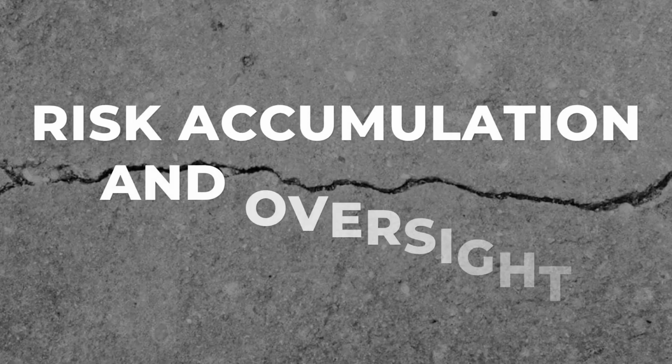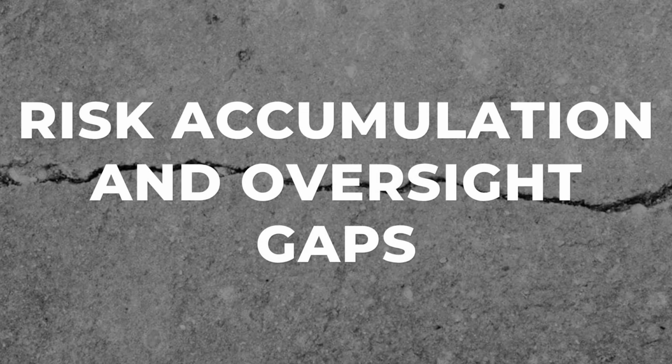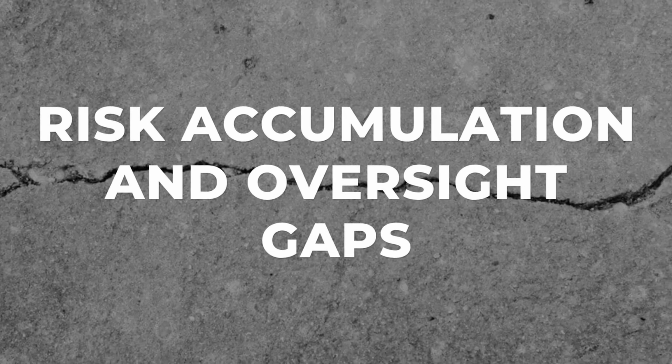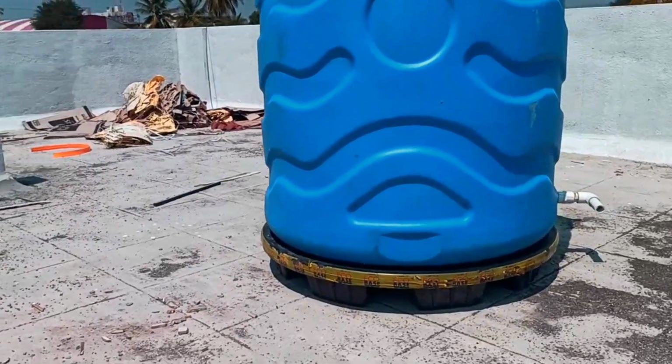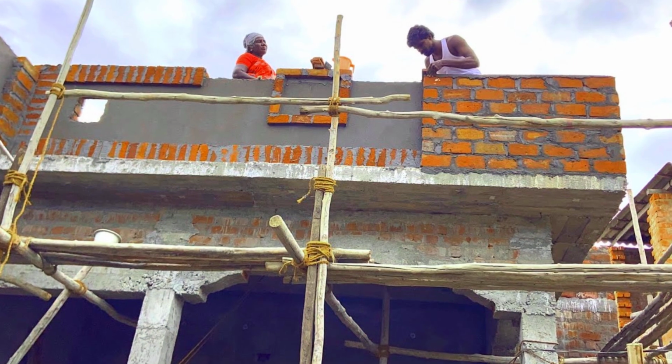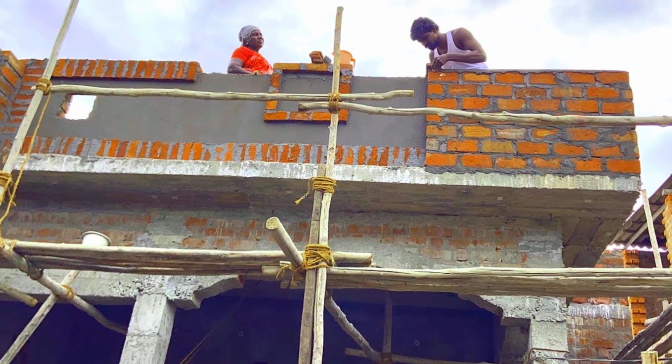Structural fatigue in reinforced concrete begins quietly, often invisible to the naked eye. Each time a rooftop slab bears the weight of a resident, a water tank, or a new partition wall, it experiences a load cycle. Laboratory studies in Mumbai have shown that when these cycles exceed 30,000, especially under sustained overloads, fine cracks begin to propagate through the concrete.